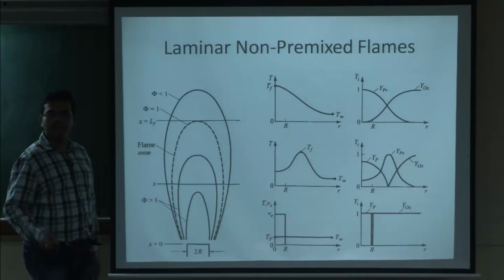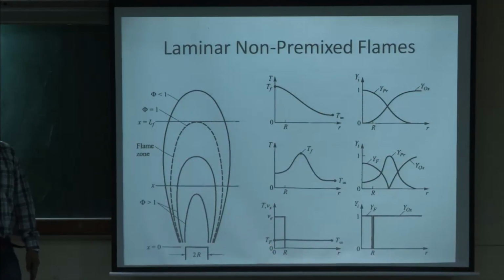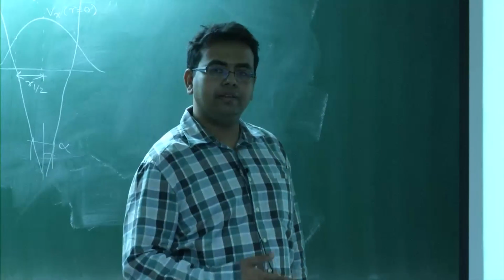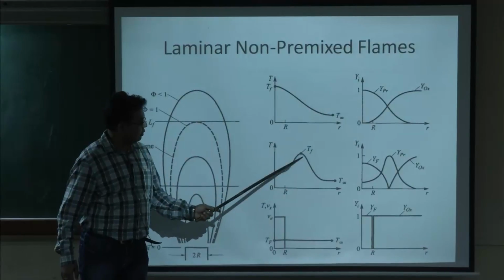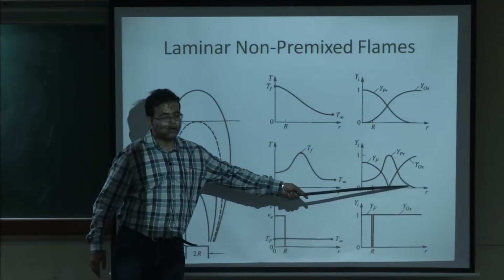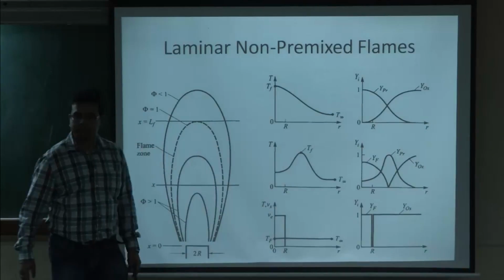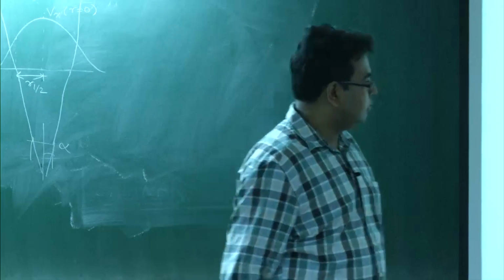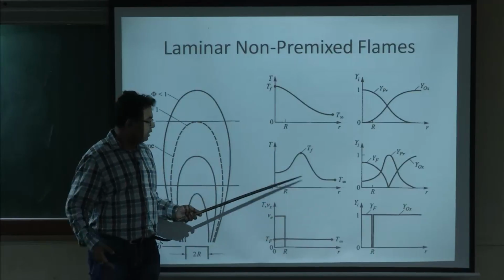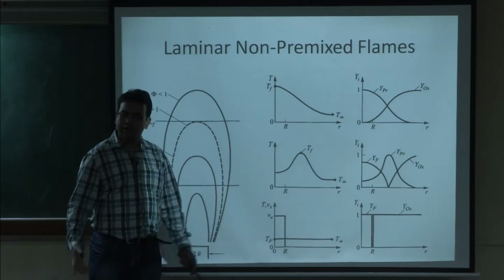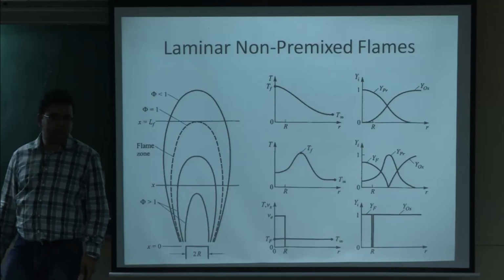So, that is the region where fuel and oxidizer are meeting in the stoichiometric proportion, and you are seeing the flame, and you see the high temperature region at that location, okay. So, this is the product that is getting formed, okay. So, basically if you scale down the temperature, then it almost behaves similar to the product mass fractions, okay.